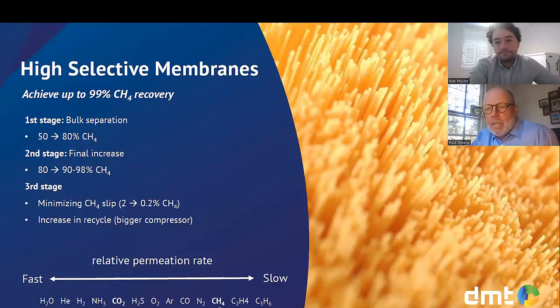On CO2, what kind of CO2 purity can you get in tail gas, and how does that tie into potential reuse opportunities for CO2? Well, we have a methane slip of 0.2%, but of course the tail gas is going to be a little bit less volume. So usually we like to say it's never higher than 0.5% methane. And of course we're actually developing liquefied CO2 add-ons to our plants because now everyone wants to capture the carbon dioxide for both credit use and for alternative revenue streams.